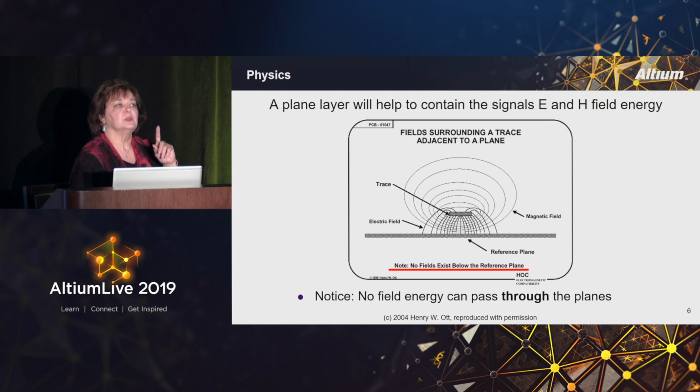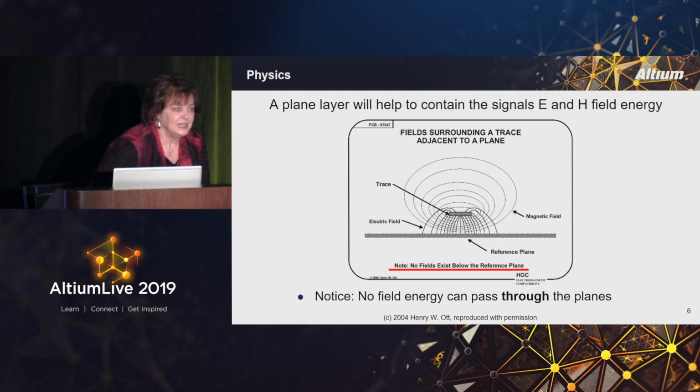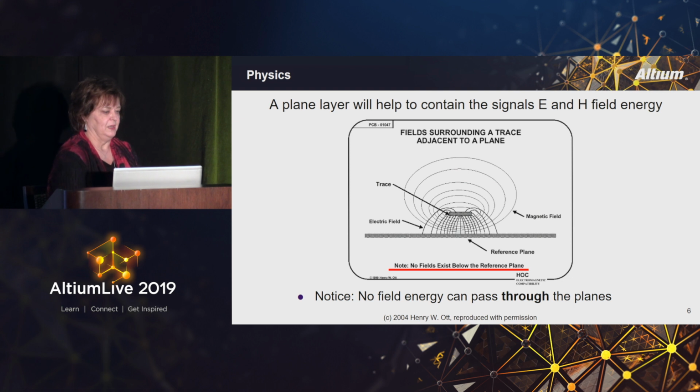or more critically, it will go to the closest metal that you have on the board. That could be traces. That could be anything that you didn't want it to be. So you have to consider and place a plane next to every routing layer on the board because you want to make sure that you can control everything that you have right here whenever possible.